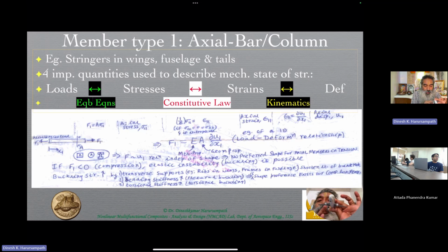So you would see that in such a situation, you will have the thing that is to be taken care of, the bending in the other direction. But since it's very small, unless it is an aircraft which has to maneuver in certain very complex ways, so that the lift distribution in the other direction also becomes a critical situation in the VN diagram to take care of. So that is as far as the F1 U1 relationship is concerned. And here you see this is what we have as far as tension is concerned.